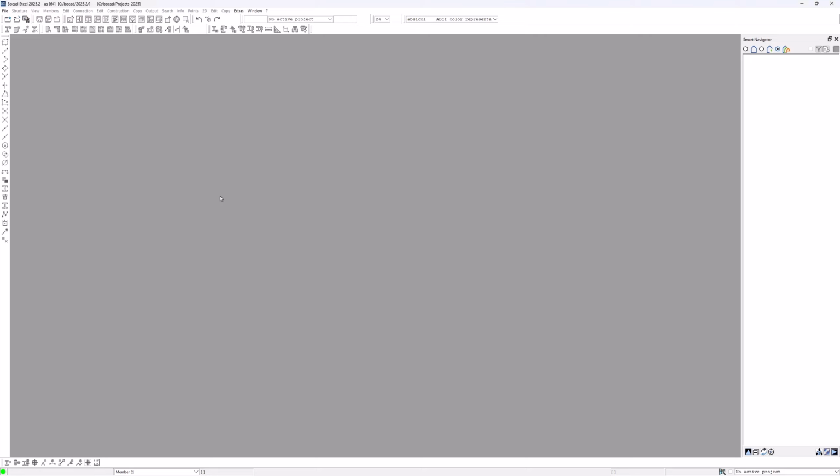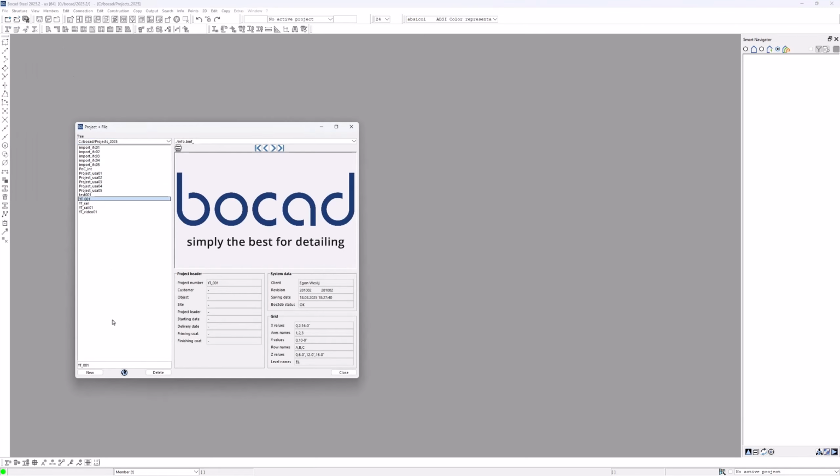So in this video, let's start a new job. So File, New, give our project a name, EX01 for example. Spaces are not allowed, underscores and dashes are no problem. I would also not recommend really special characters, in case you enter something with an accent or something like that. I would not necessarily do this, but feel free to. Apart from those small things, enter any name you want.